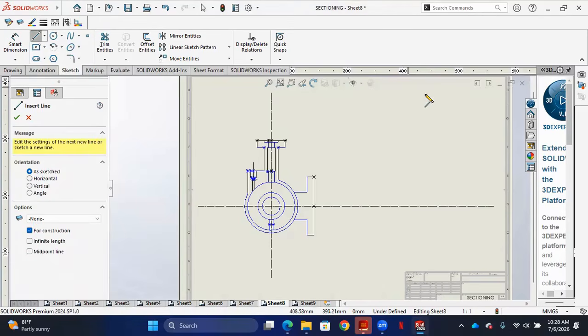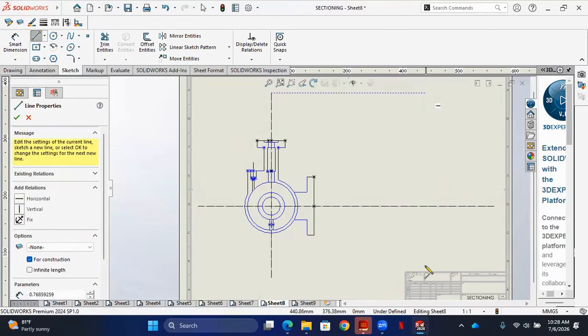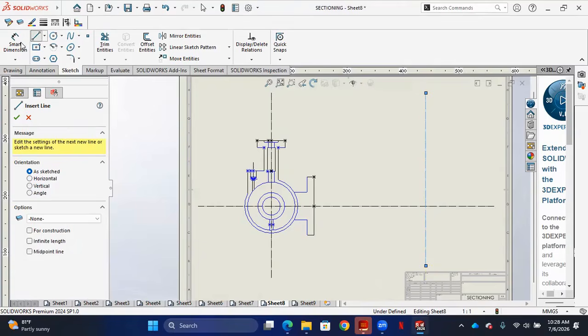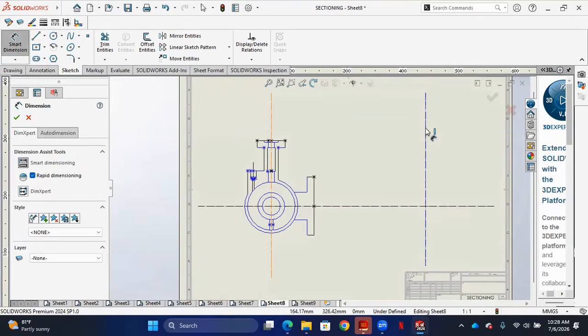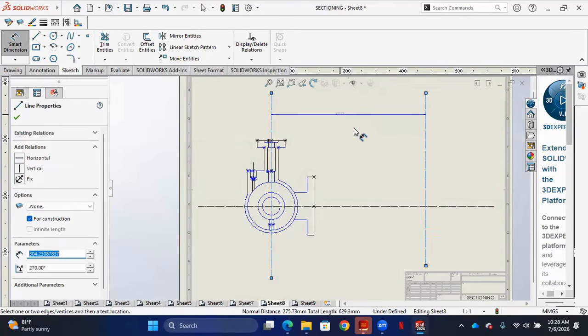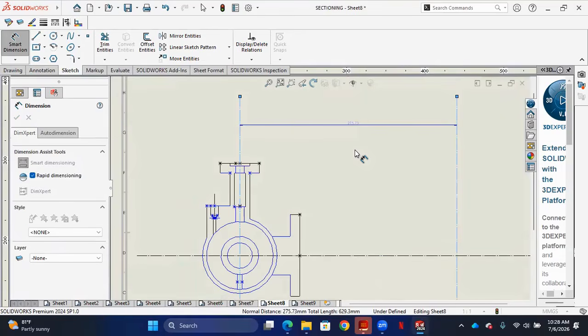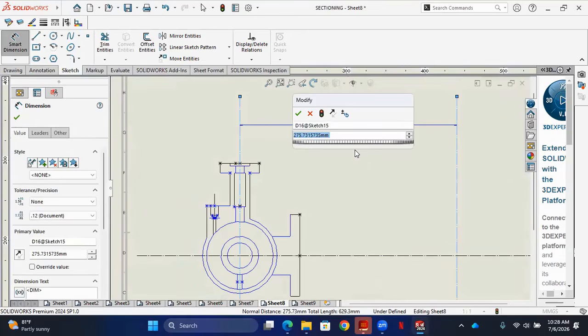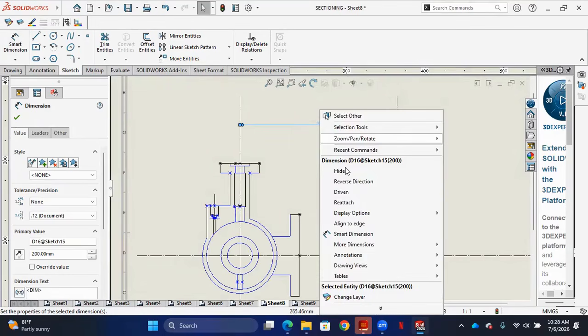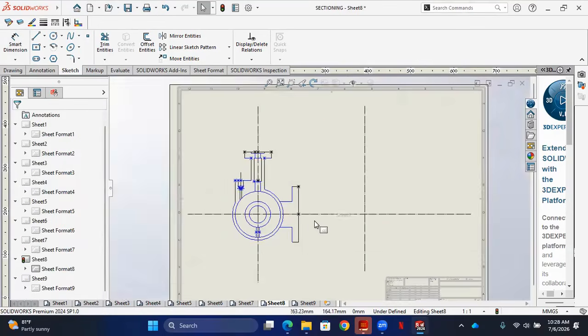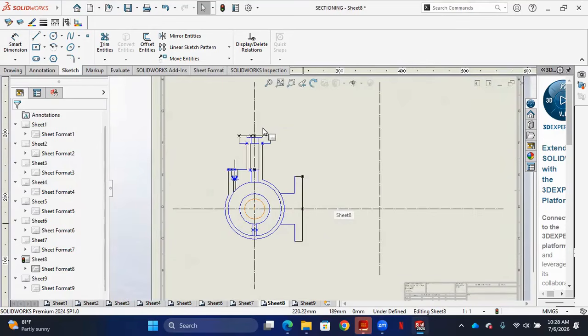So I draw my vertical line. Then I'll measure from this point to the other vertical. I'm going to measure 200 so that I'll be safe, so that the drawings don't interfere with one another. So I draw my 200. Then this one, because you've already drawn this side, you just extend the line, because they're in line, so you just extend them.